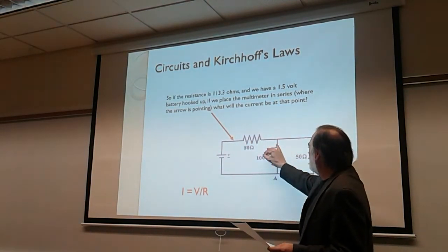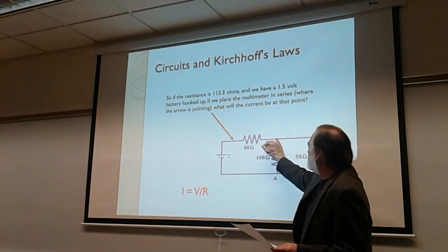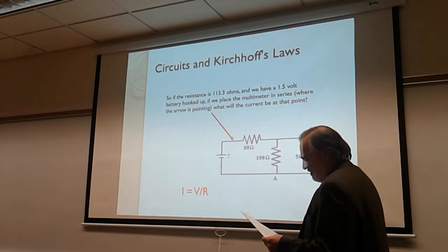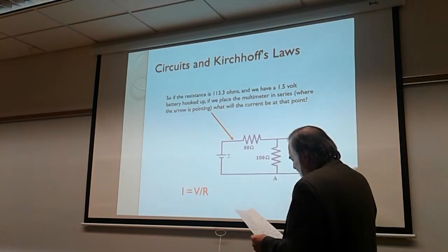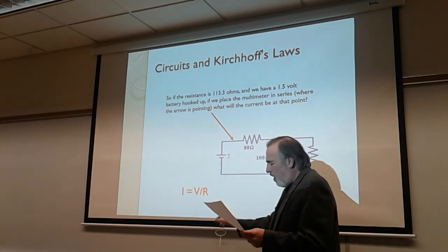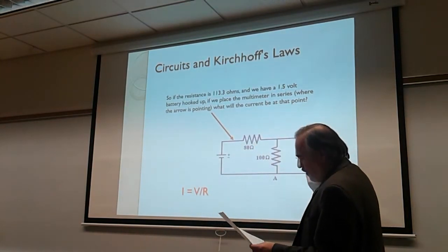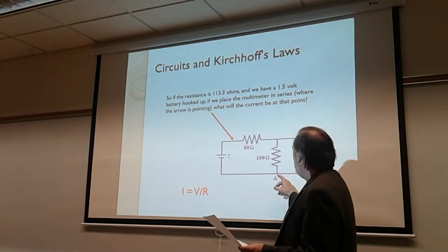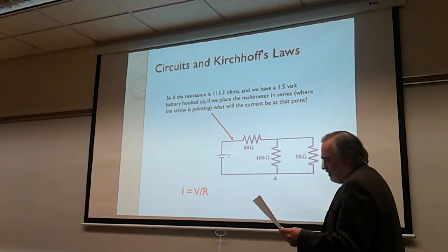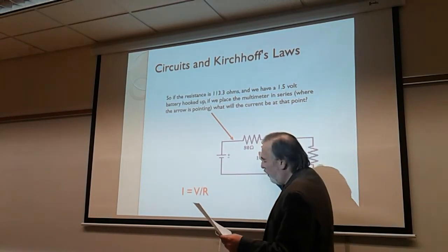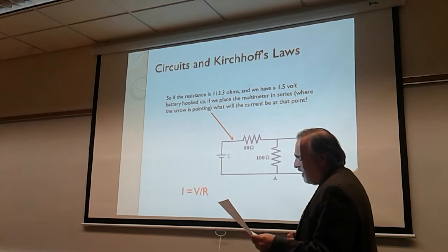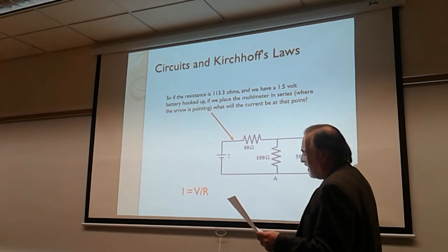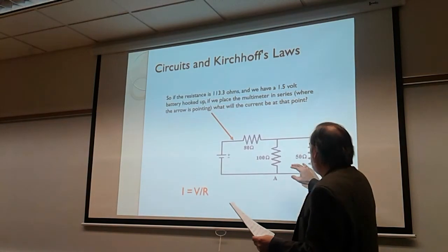So now we hit this junction. So at this junction we have to split. How much we split depends upon the resistors on each side. In this junction, we could do this, I equals V over R, Ohm's law, and take that 0.444 volts over 100, which gives me a 4.44 milliamp amperage into this junction. Again, I'll give you the sheet of paper that'll explain a little better.